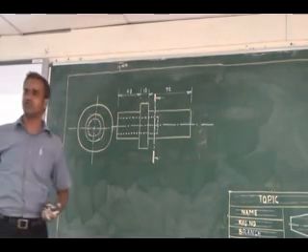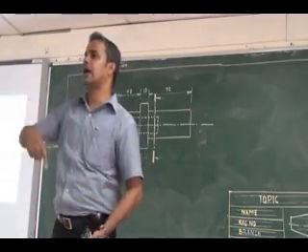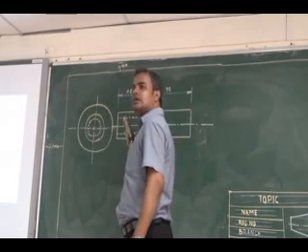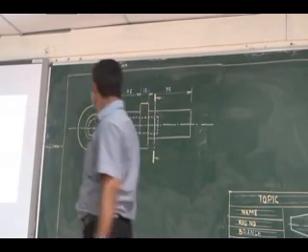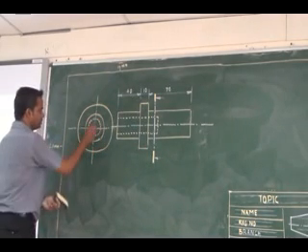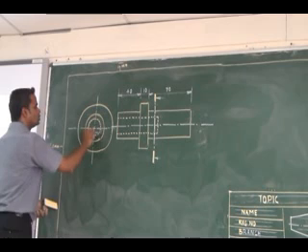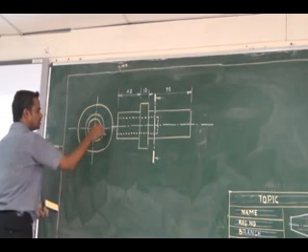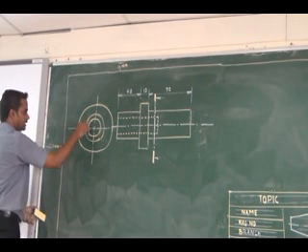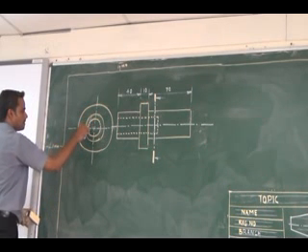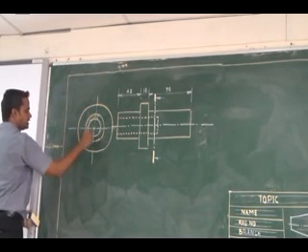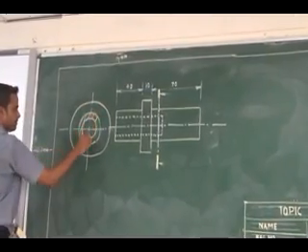That cut portion I can show as a hatched line. Wherever the cutting plane intersects and cuts the material, that portion is shown as a hatched line. So this is a sectioned portion. Now the dotted line goes off because I am going to show the section line. So here I can introduce a hatched line. About hatching, we'll see.